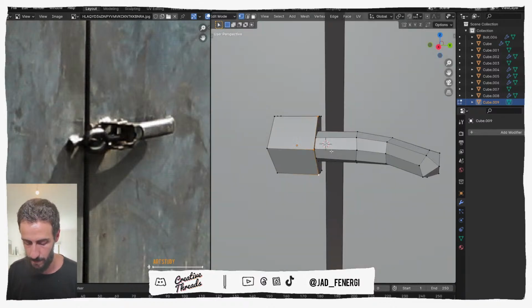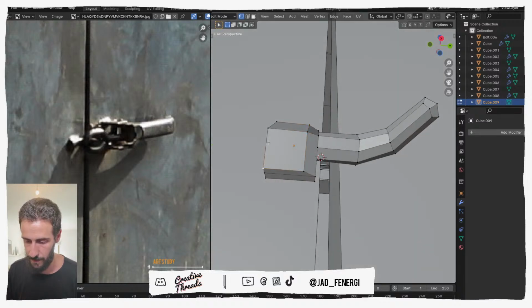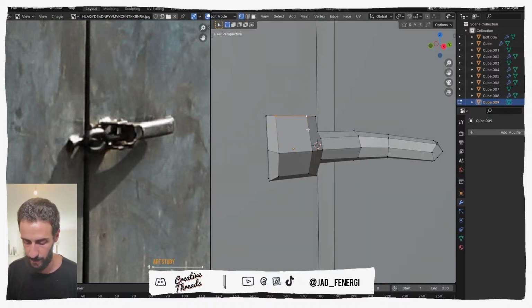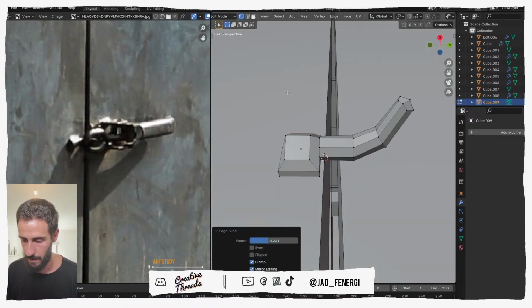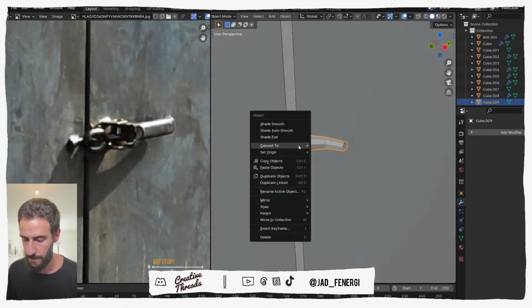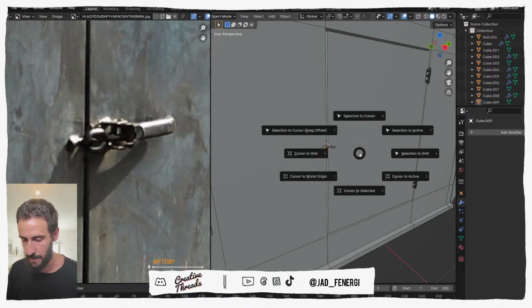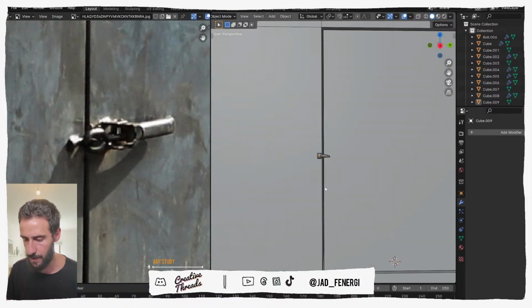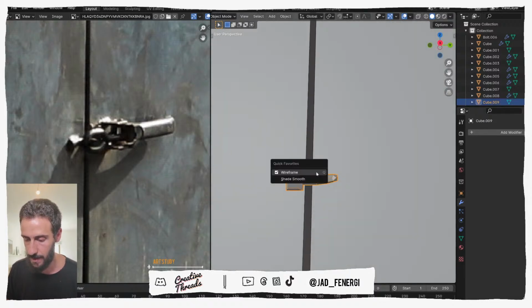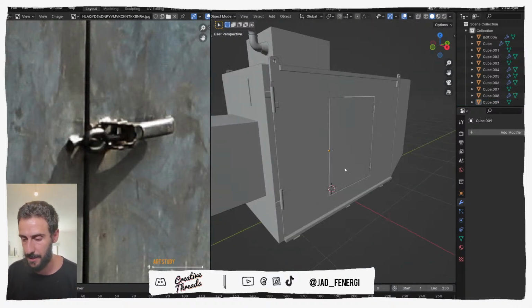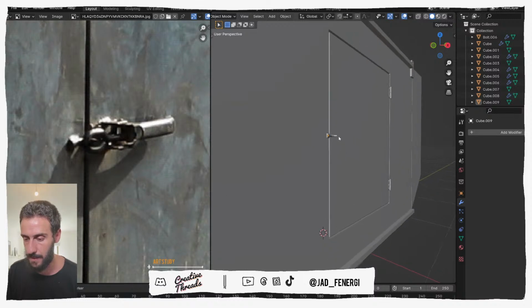And just following some visual cues in here. I'm not trying to be accurate or anything. So just moving vertices around. Yep, that's good enough. Right click, shade auto smooth. So first, let me Shift S, cursor to origin, just because it's a bit distracting. So this is very low poly, even with this mode. But it's a decision of, are you going to see this close or not?